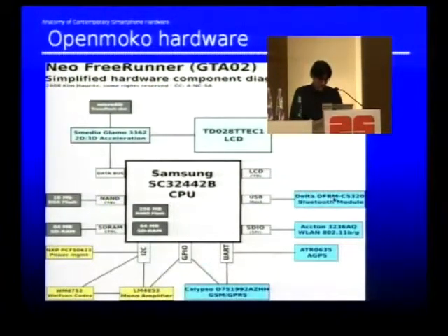There is another connection between the Bluetooth module and the audio codec over here, but the person who drew that diagram, obviously it's hard to draw a line all across the diagram, but that's the PCM bus between the Bluetooth and the codec over here. Yeah, we have an LCD controller that is obviously connected to the LCD, not disconnected, and there is, oh no, sorry, no, it's actually true. The LCD controller is not used, the built-in LCD controller of the SoC is not used in this hardware revision, but there is a graphics accelerator, in quotes, connected to a display module.